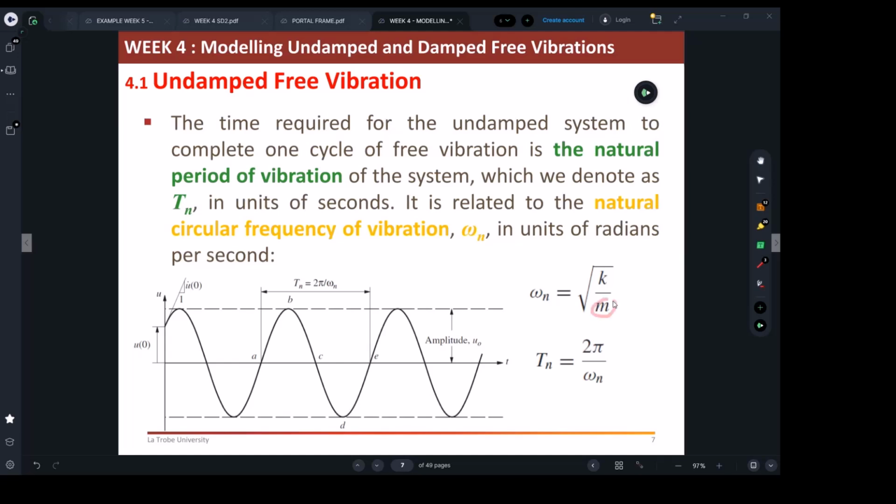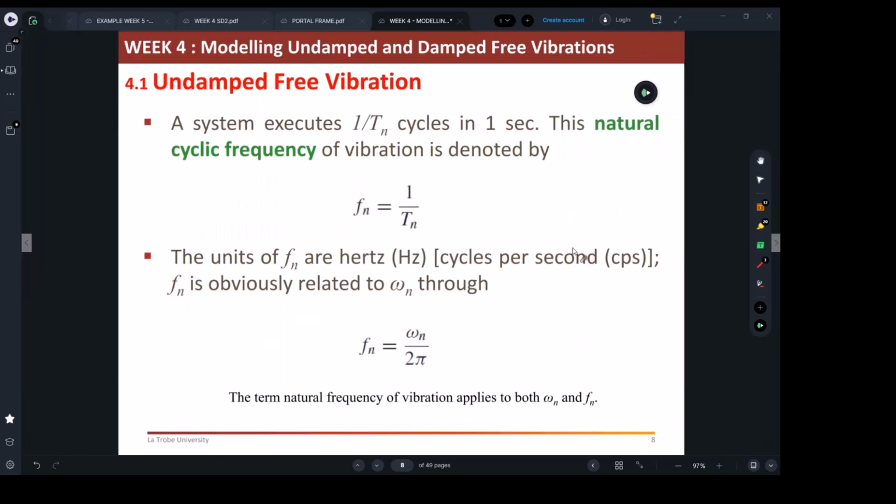So they changed the mass of their new structures and started researching timber a lot, because basically they want to change the frequency. But for existing buildings and towers, this is difficult to change. It needs to be concrete, so you can change stiffness, or as you're going to see next week, we can play with damping. Damping can help us control as well. That's really the main message of what we're working on, not only today but over most of the weeks.